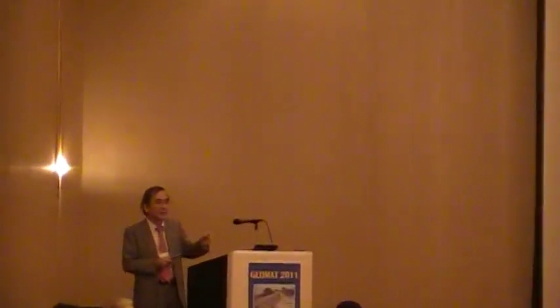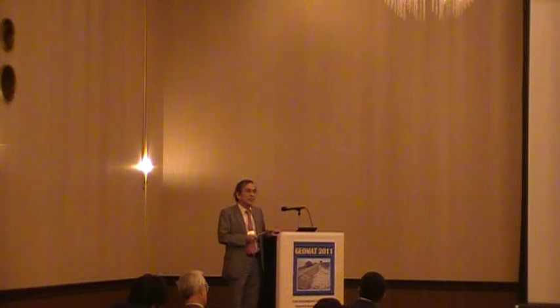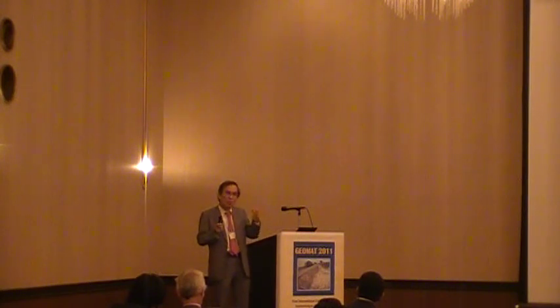Yeah, when you measure that on the slope, part of the settlement is due to seepage induced deformation, plus then you have settlement due to consolidation also. Yeah, but in the base land we use the same materials, compacted 90%. Well compacted. So it's 1 for 7 meters, but it's not so much.